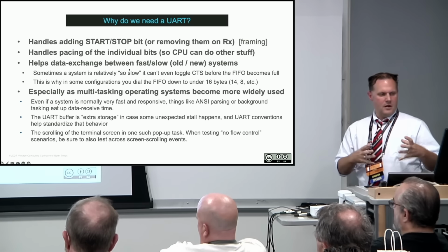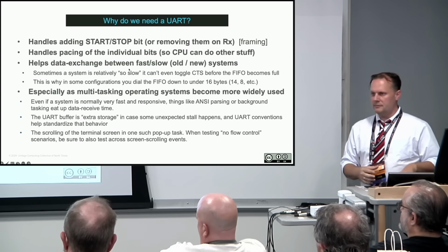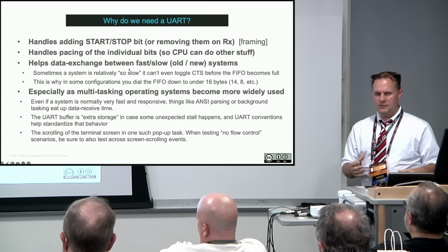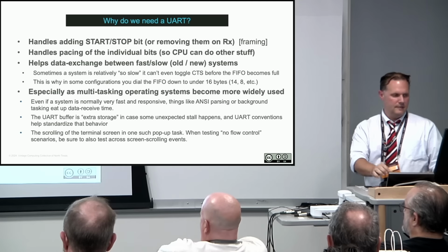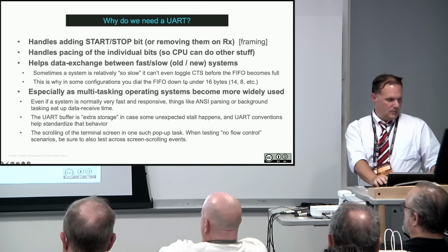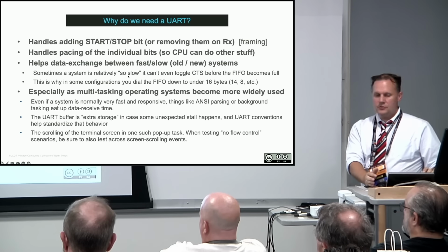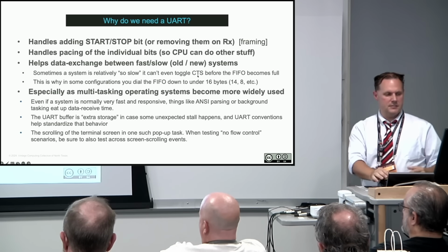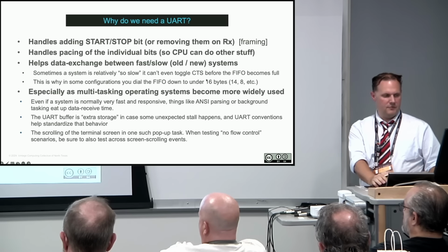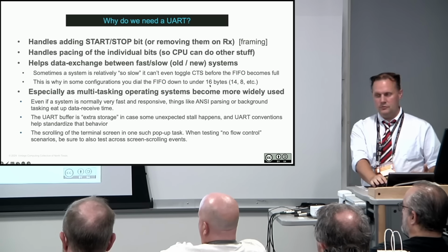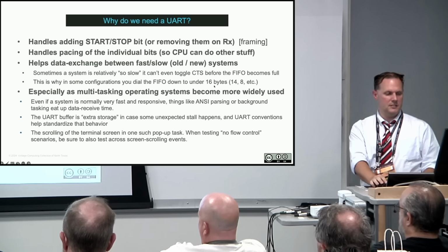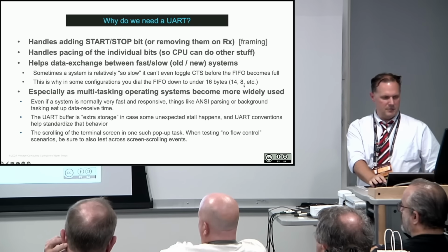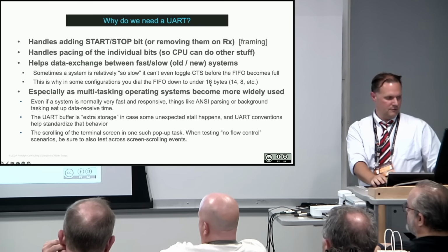It kind of helps as a throttle, as all the UARTs will have some amount of buffer. So if you have a slow computer talking to a fast computer, it can help buffer some of that. I've seen some computers that are so slow, it gets the signal to stop, but it can't stop fast enough. It kind of has a momentum of that information. So I've learned that sometimes that's why you might want to tune those FIFOs. Don't use the full capacity of the 16 bytes. You might move it down to 14 or 8. You might start at 8, start at half, and see if that works, and go from there.